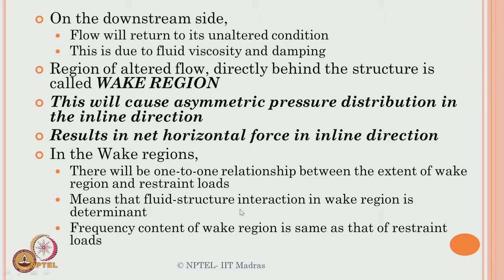On the other hand, you see here the frequency content of the force component remains at a similar value as that of the restrained loads. It means you will see that the wake region invoked forces are in resonance with the restrained loads. So, this induces, though in multiple frequencies, an additional force on the wake region, which is on the downstream side only for a specific sector, beyond which the flow becomes unaltered again. So, it is not only the inline flow direction that is important, it is not only the transverse direction, it is also the downstream side sector which is disturbing the flow medium, which causes forces on the member.